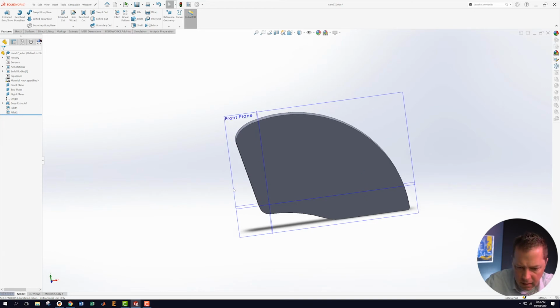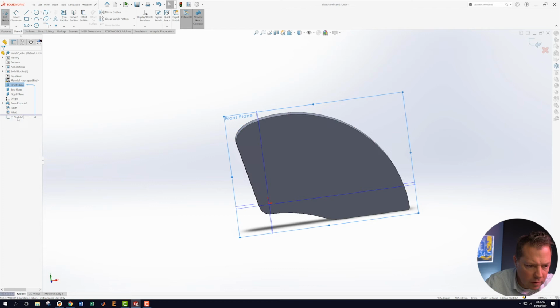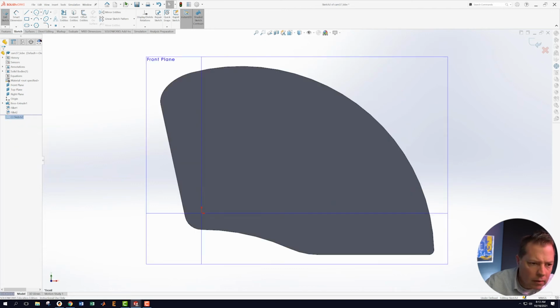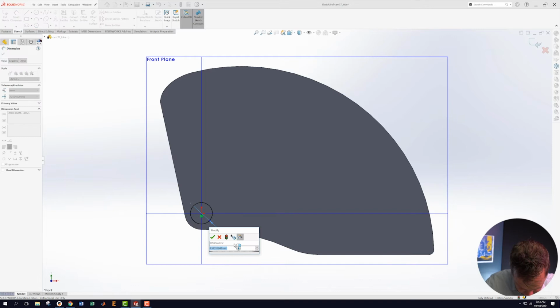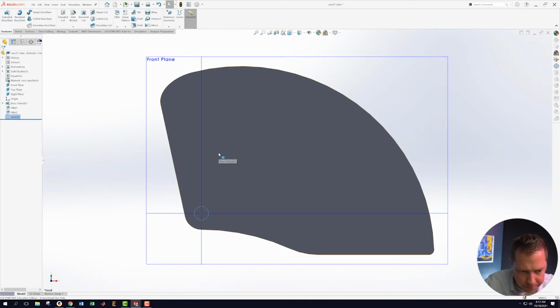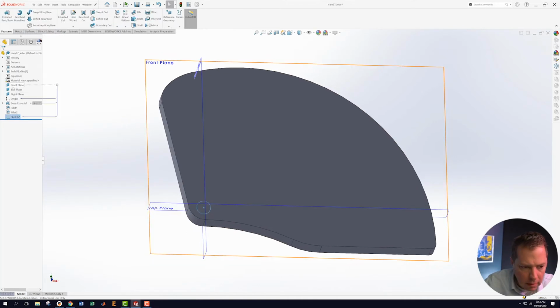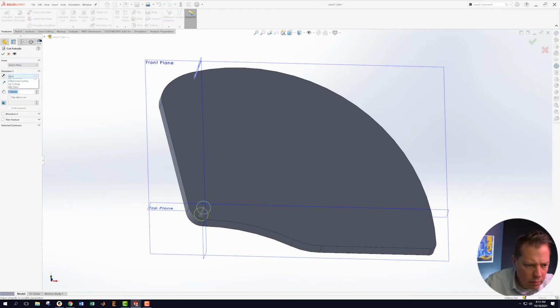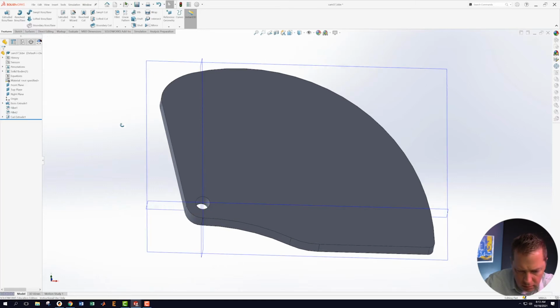Okay, let's get some of these holes in here. So we've got a hole that's right in here. And this hole is, oh, there it is, 5.5. That dimension was in the head, that dimension was on the shaft. These are probably clues that these things all are related to the assembly. Extruded cut. Okay, through all both is what we want. Great, there's that.